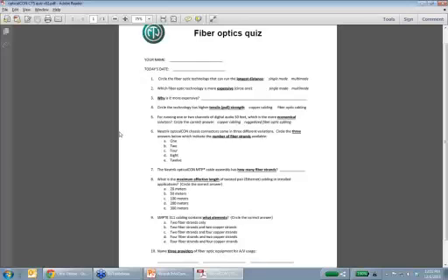Does anyone make a combination multi-mode and single mode cable? It's not possible. Good question. You cannot have both, because multi-mode is 50 micron and bounces the light up and down, while single mode is 9 micron and shoots the light straight through. But there are transceivers which can operate on either.